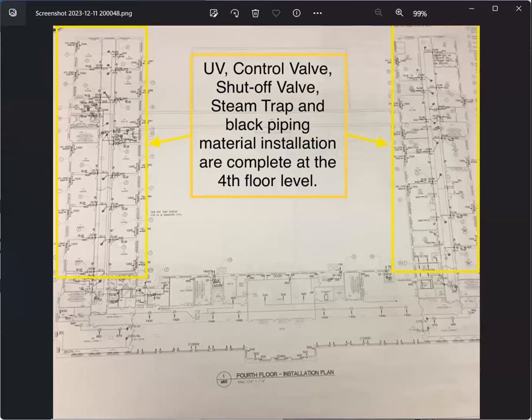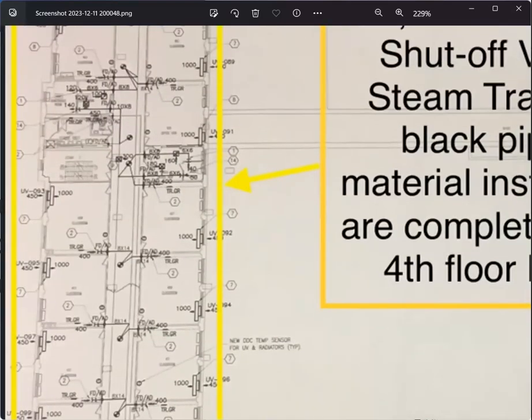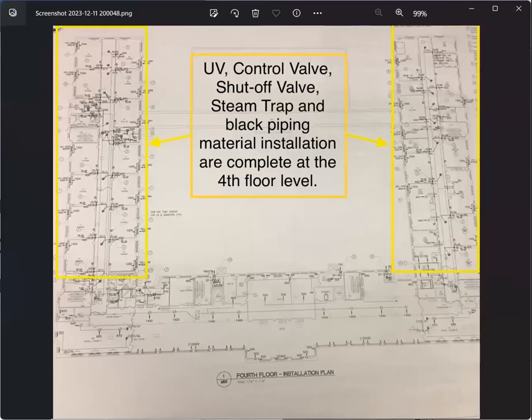And that's it. So this is the whole drawing plan that I have inspected, and I label it like this, what installation I have verified for the job and what is not installed currently, like the ductworks and the fire dampers, that I'm going to come back for once they have installed them completely.